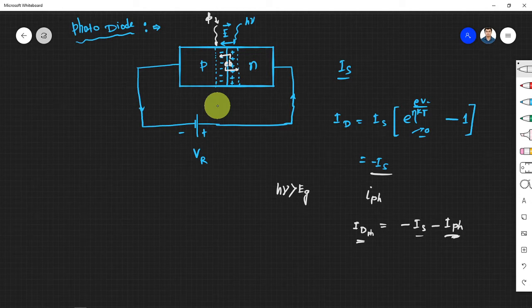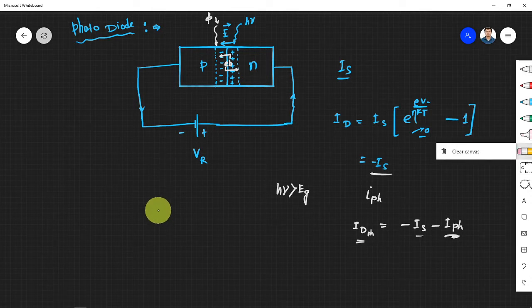So in an ideal situation, we don't connect the diode directly to the battery. We use a resistor actually. So let me just put the resistor here. We put a resistor across, and then only we connect. Otherwise you will burn the diode, right? If this voltage is higher than the reverse breakdown voltage, the diode will break the junction otherwise.